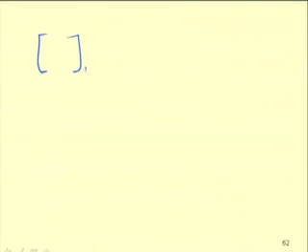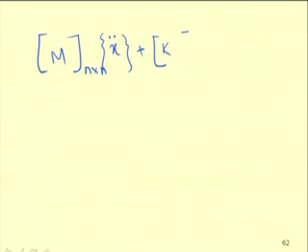So, for a multi degree of freedom system similarly, one can have an n cross n mass matrix. If it is an n degree of freedom system, then it will be an n cross n mass matrix, and it may be written as M X double dot plus similarly K X. K also will be n cross n. This is equal to, if this is a forced system, then this will be replaced by F.